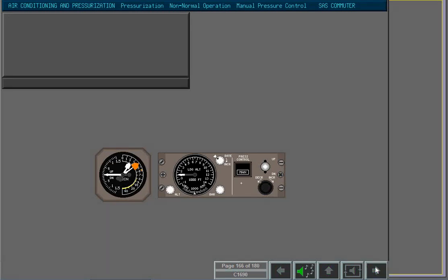The pilot can switch from automatic mode of pressurization to manual mode if the pressurization system is operating normally. Pressing the pressurization control push button switches the modes. A white MAN annunciation is presented to confirm this action is successfully completed. If the pressurization controller push button presents the amber fault annunciation, indicating that the automatic mode of operation has failed, manual pressurization must be adopted.